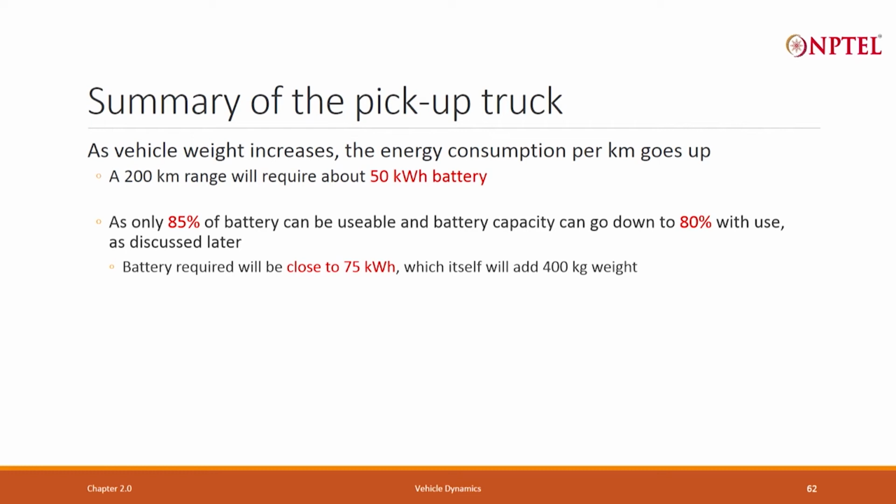As 85% is used, and finally, it goes to 80% because the battery deteriorates, and still it should give me 200 kilometer. My requirement goes to 75 kilowatt hour. I will look at this 85%, 80% number in greater detail later on.